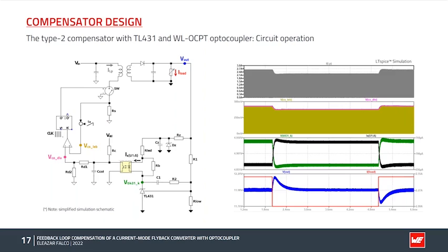The results used here were taken with a simulation in LTSpice, and the signals probed were the transformer primary current, magnetizing current in gray, the voltage across the sense resistor after ramp compensation applied in gold brown, the compensator output voltage in pink, and this is after being scaled down by this resistor divider RD1 and RD2, which are internal to the controller which we used, the NCP12700.